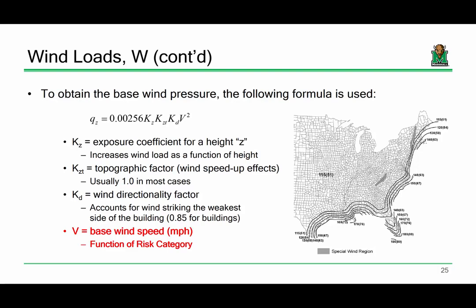It's just Bernoulli's with a unit conversion in it. So you have point A with a velocity and no pressure, and then point B has no velocity. What's the pressure at point B? So it's just Bernoulli's equation. It's pretty straightforward.